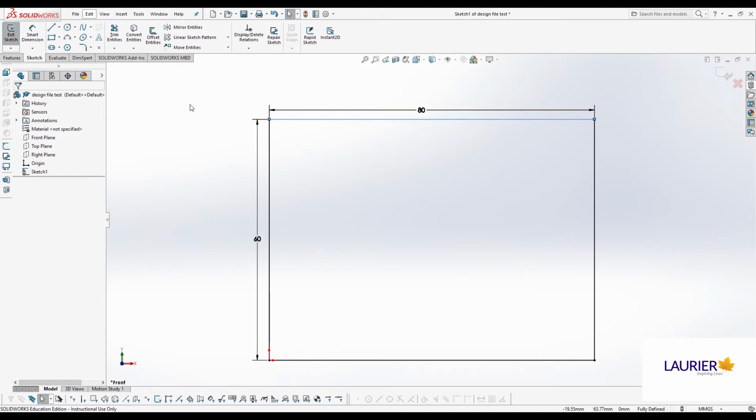And then the 5th one is where you add a dimension that, because of some other property, if you edit it, would cause something that is true to be untrue. So it can be fighting with another dimension, or it can be fighting with a midpoint. So if you take a line and you dimension from one end to the midpoint, and then you try to dimension from one end to the other end, you're going to get this same error because you've got 2 editable dimensions that you can't change independently because they're locked together by a property, that property being the bisecting length